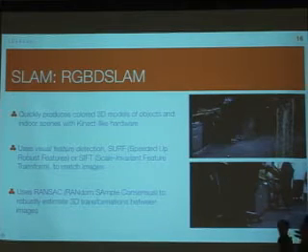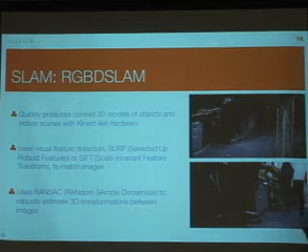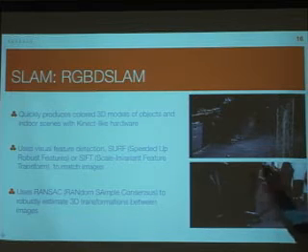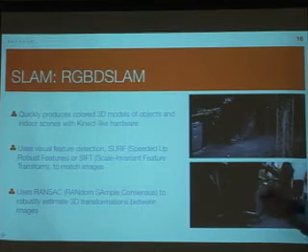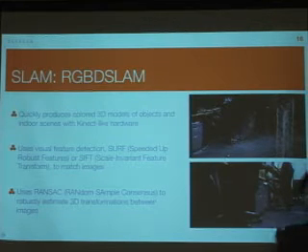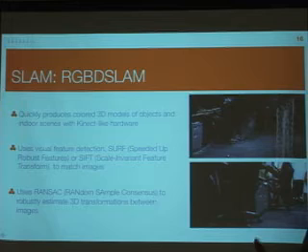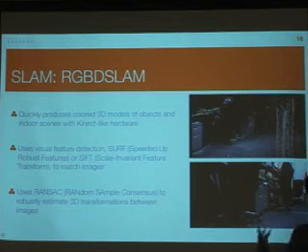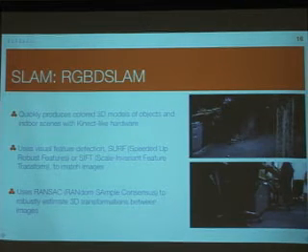It's collecting the RGBD, which is the color feature, and also some straight corners of the scan. So it uses only those features to localize itself rather than stitching all the scan data that it has. So these are the two SLAMs that we implement on our project, Slammr.